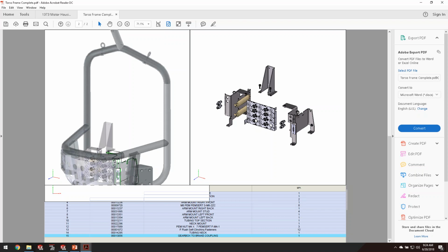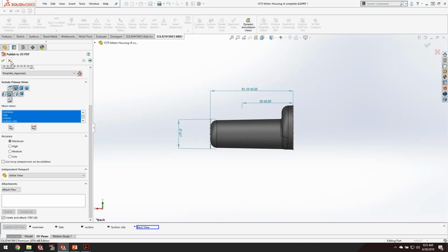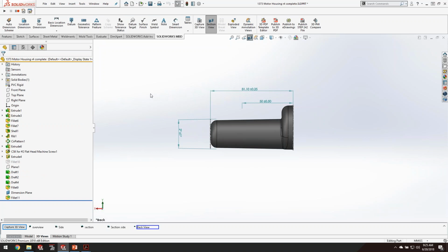Another question came through. Can geometric tolerances be automatically passed through to the CAM process so it won't need to be manually entered and interpreted into the CAM system? So that's a good question, and some of it is dependent upon the CAM solution that you're using. So for SOLIDWORKS CAM, we can use the DimXpert function.